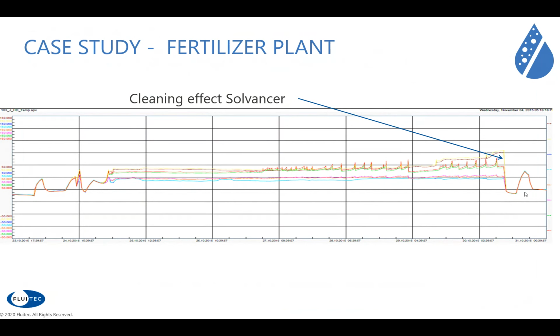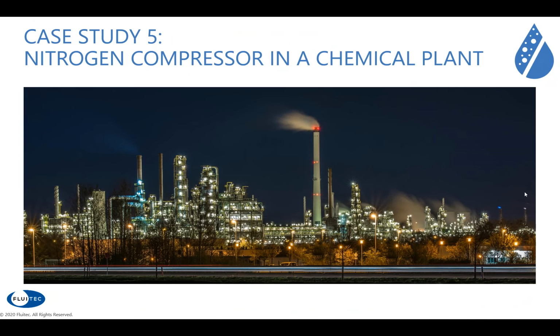here is that the cooler was not cleaned. In between the oil changes, they forgot to clean the cooler, and what we can recommend, also with gas turbines and steam turbines and compressors, is when you do a revision and you are changing oil, do not forget to look at your cooler. It can build up a lot of varnish, and then with the new oil, it can dilute and solve again some of the varnish, again entrained to the bearings and building up these deposits.